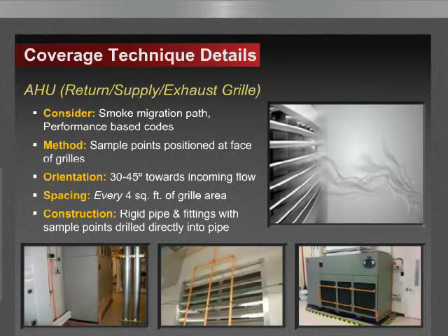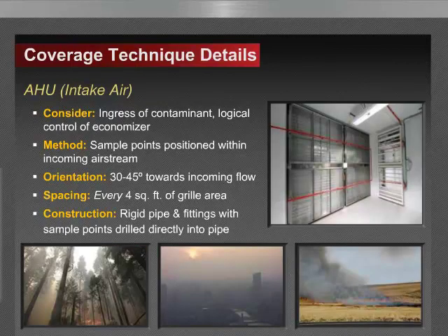So, a similar approach is often applied to fresh air intakes, as the fresh air coming into the building, as a means to monitor incoming air, which may carry contaminants such as smoke-laden air from forest fires within the vicinity, or the occasional crop burning, should the facility be located near farmland.